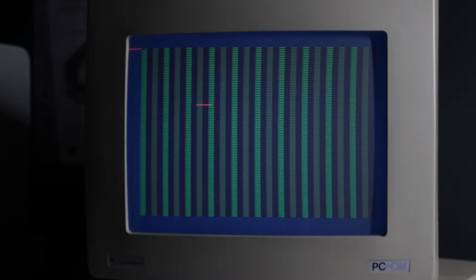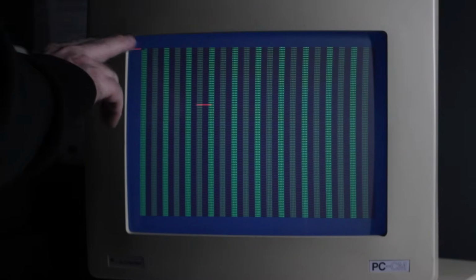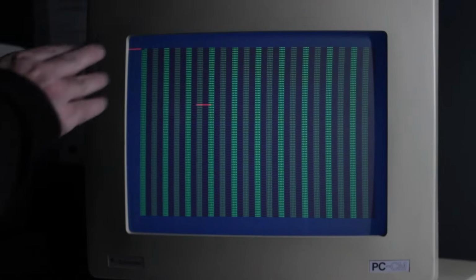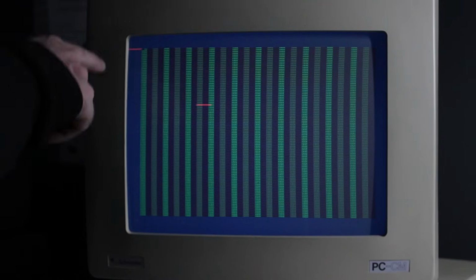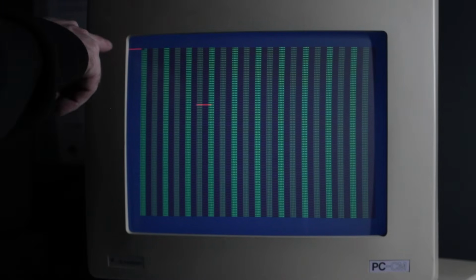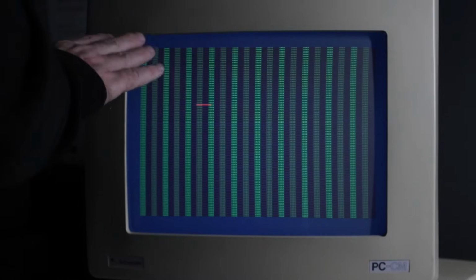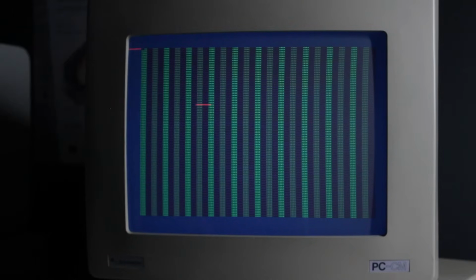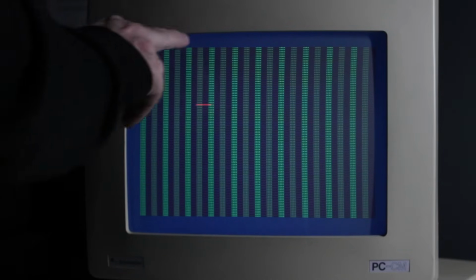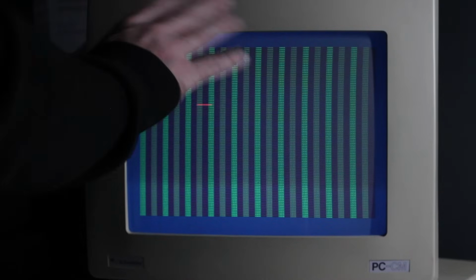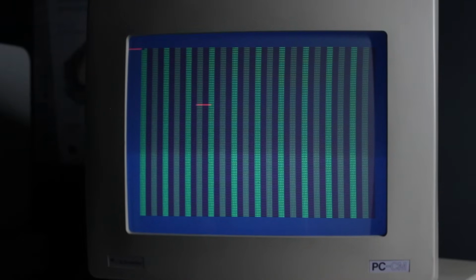Well, this seems to have been more or less successful. I padded things out so that the jitter is now happening just before the start of the active region. And actually I'm now doing a DRAM write. So I'm writing a single byte to video RAM, and I'm doing it just before I do this background color change. And what we'll see is, as we move this thing slowly across to the right, we'll find that there are certain character positions that it can sit in and certain that it can't. And the ones that can't mark out those wait states.